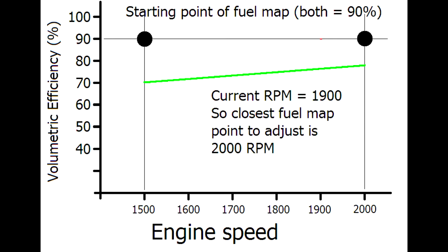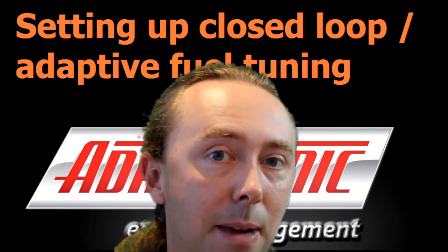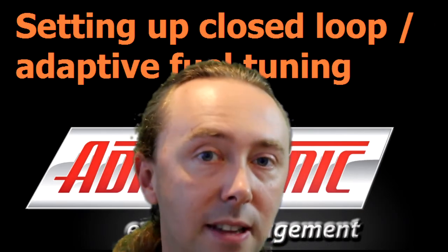This can cause a very bumpy fuel map, and the way to fix this is to start off with values that are closer to where it needs to be. So in most cases, the most efficient way is actually to start off by roughing out the map by hand and starting off by saying what values it needs in the map to get pretty close to the target AFR, and set large regions of the map to that percentage.